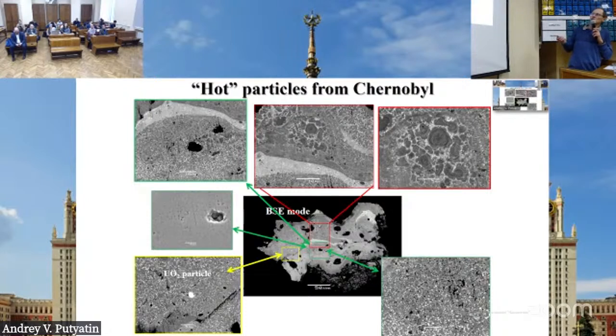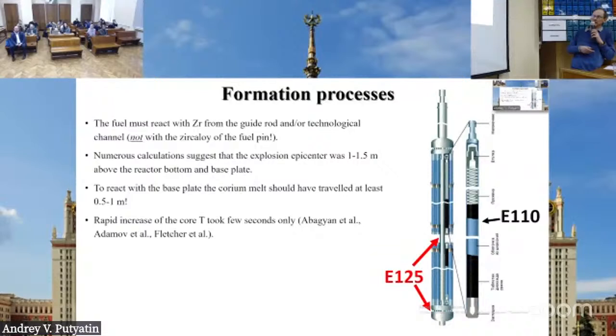And here, certainly, you have some traces of thermoplastic flow. So uranium dioxide was interacting with cladding, and the cladding was ductile, so it was flowing. And when it was cooling down rapidly, when the particle was expelled, there was a very interesting, from a crystallographic point of view, precipitation of a crystallographically ordered phase.